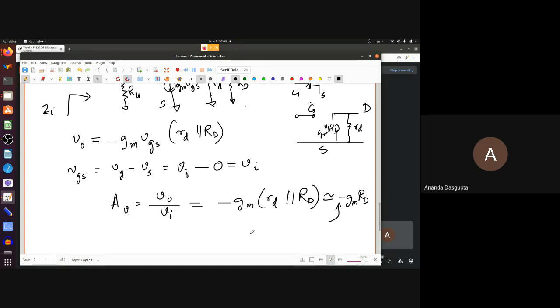Yeah, that's exactly what it means. Or actually, a more formal way of putting that would be the output is 180 degrees out of phase. That is, VO is 180 degrees out of phase with VI. So when VI reaches a maximum, VO reaches a minimum, and the other way around.